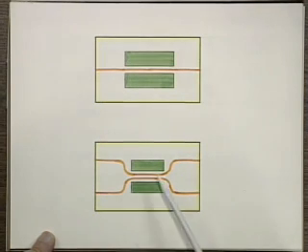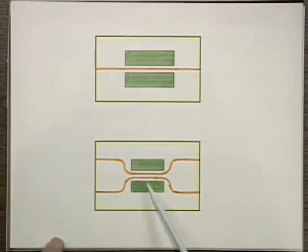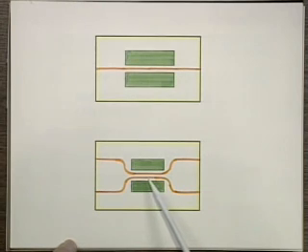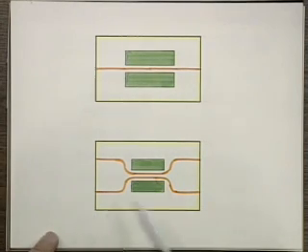If you want to have a variable coupler, again, if the substrate material is electro-optic, then by putting electrodes on the material, you can change the index between the cores, and this way change the coupling. The coupling ratio will change depending on the index. So I can couple more light or less light by applying a voltage. This is a neat little device.